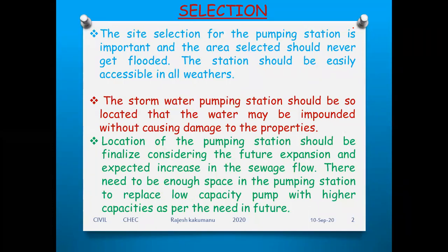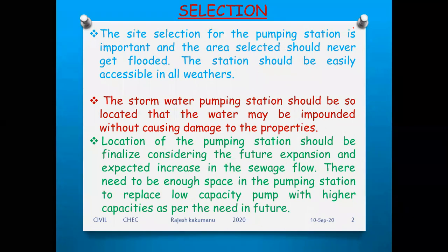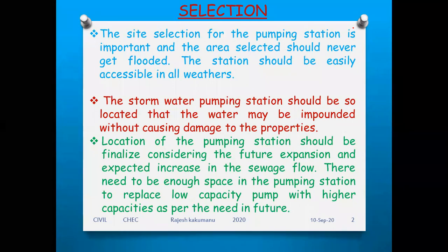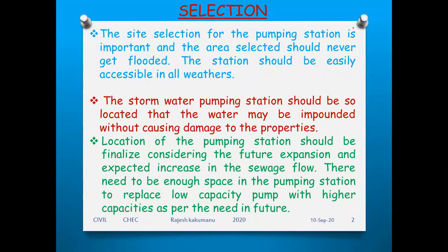In some places the water is going, municipality water or our sanitation water. Whenever you are not maintaining it properly, or the site location is abnormal, you will get some maintenance problems. That's why, when selecting the pump location, it should be accessible in all conditions, right?